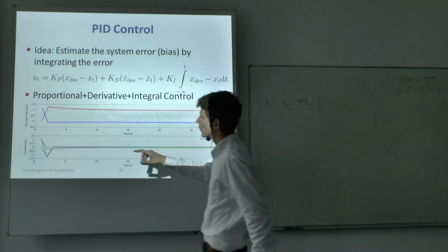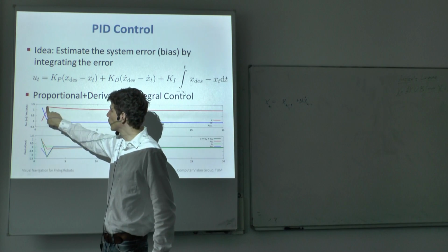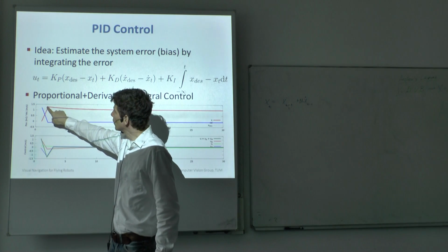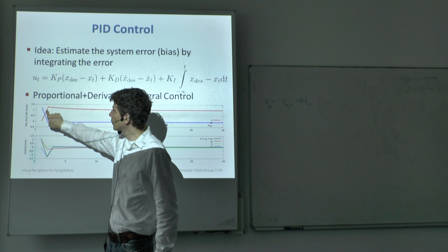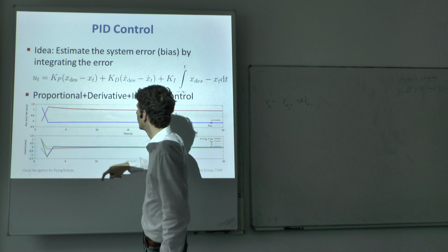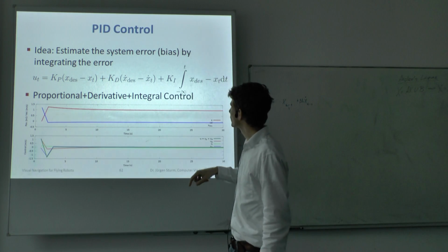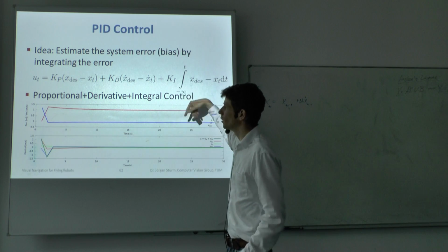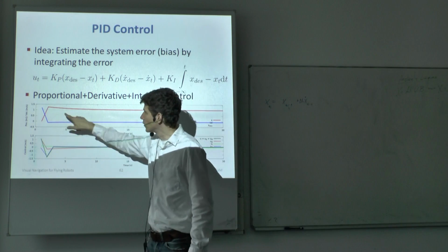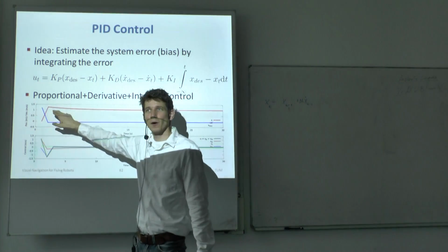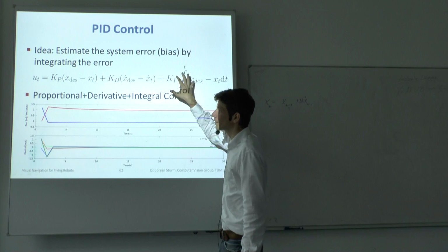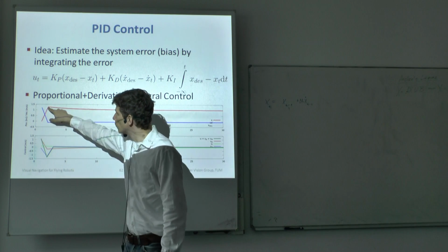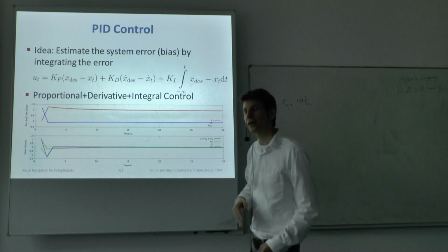So you see here, the quadrocopter is moving upwards. It's being pushed away by the wind. And now we have a certain deviation between our goal location and our current location. This will make this integral larger than 0. And the longer we are above our desired value, the larger this integral will get over time, and the more and more this integral part will pull back the quadrocopter.